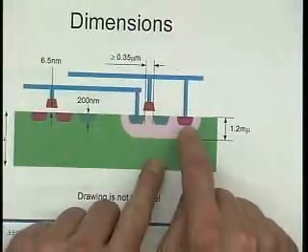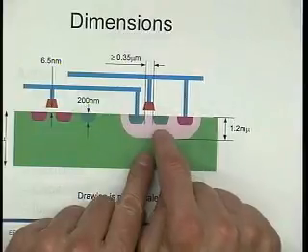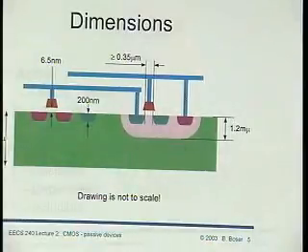Now, actually, if we look at this stuff here, then we have here P, N, P. Heck, we've got a bipolar transistor also, right? It's good to look at the cross-section sometimes. This wasn't a BiCMOS option that we paid for. We just got this bipolar transistor here. Should we care? Why?